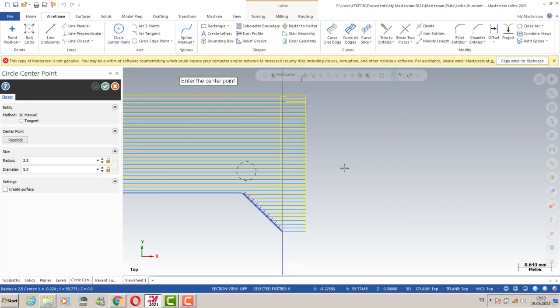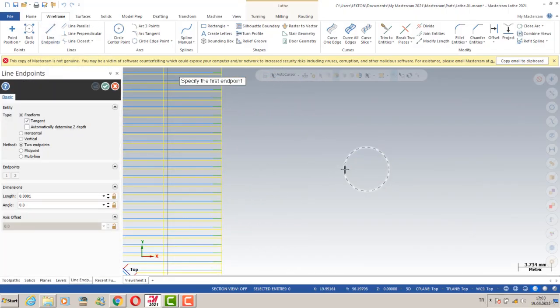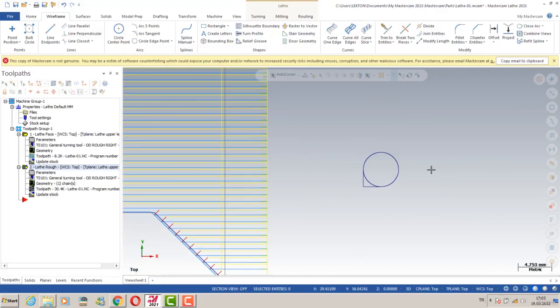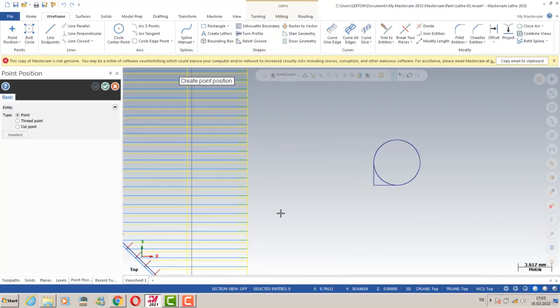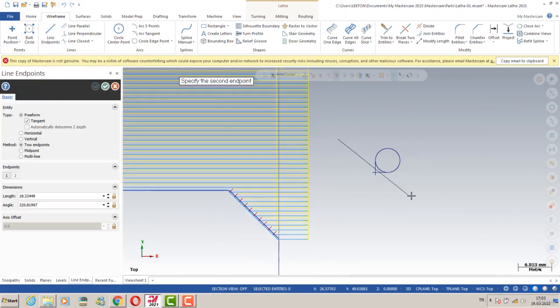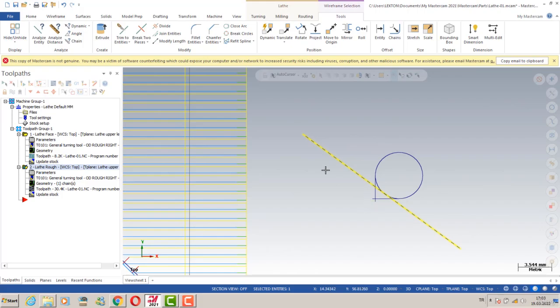This is maybe my tool diameter, 5 millimeter, and this is my compensation type like this. All my toolpath is calculated according to that point. So if you intend to cut that kind of line, this is your exact line. This is going to be your toolpath line.